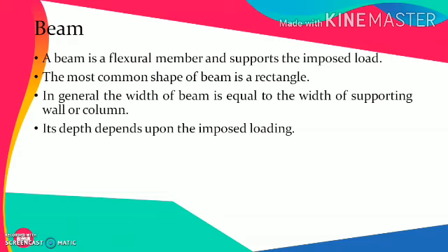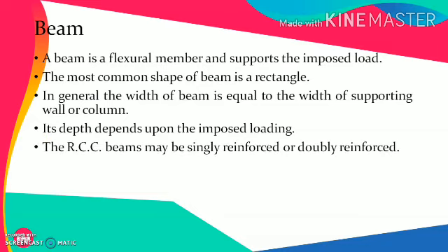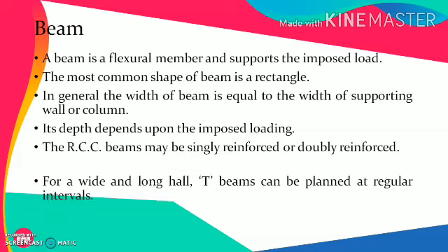Its depth depends upon the imposed loading. As the total load increases, the depth increases. Its depth also varies with the span. The RCC beams may be singly reinforced or doubly reinforced. Singly reinforced beam means it has the tensile stresses at the bottom, so the reinforcement is generally available in the bottom part, while the doubly reinforced beam has the main reinforcement at the bottom as well as at the top.